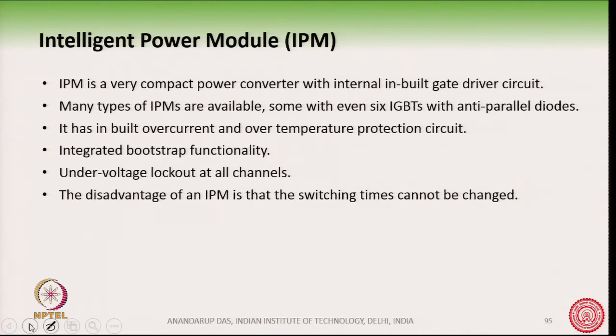It also has integrated bootstrap functionality and under voltage lockout. So, many protective features are present in the IPM, and it is very compact in size. So, where size is at a premium, where you want to reduce the size, IPMs can be a very good choice.